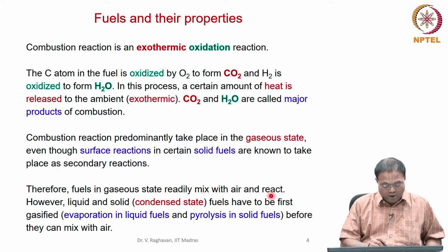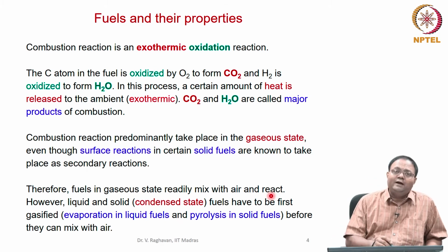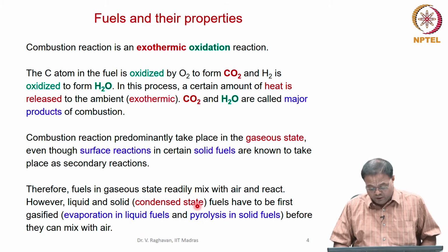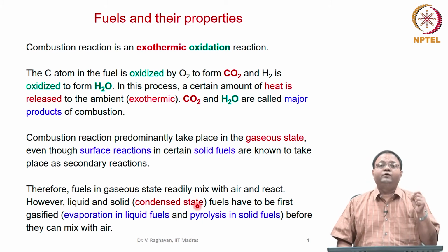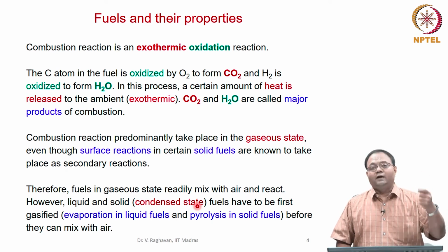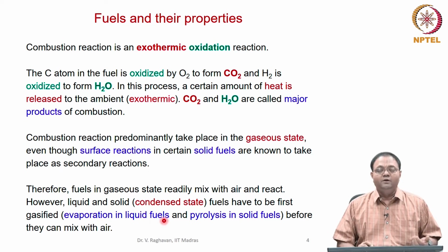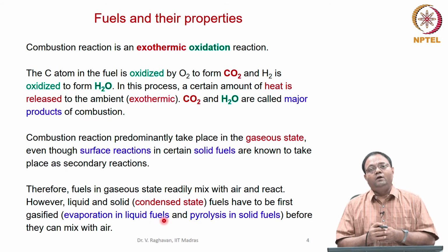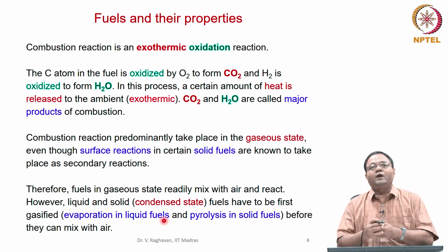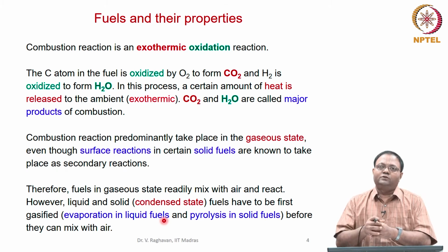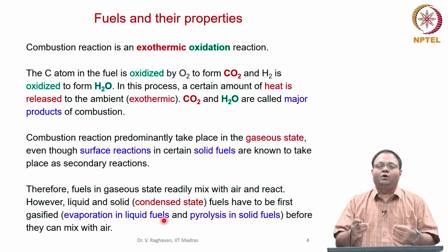On the other hand, liquid and solid fuels are condensed fuels. The liquid fuel has to be converted into a gaseous fuel by vaporizing it. Similarly, the gaseous fuel trapped inside the solid fuel has to come out and react. For that you have to heat it, so an additional process is involved.